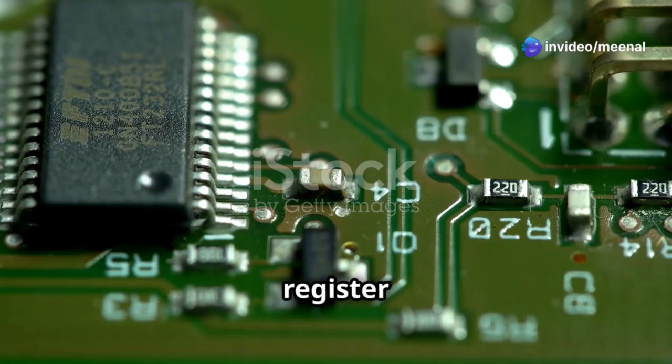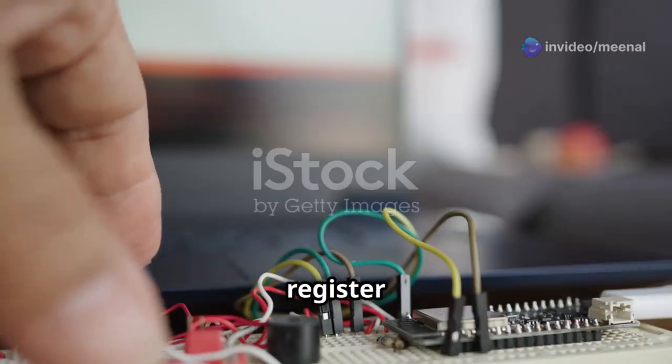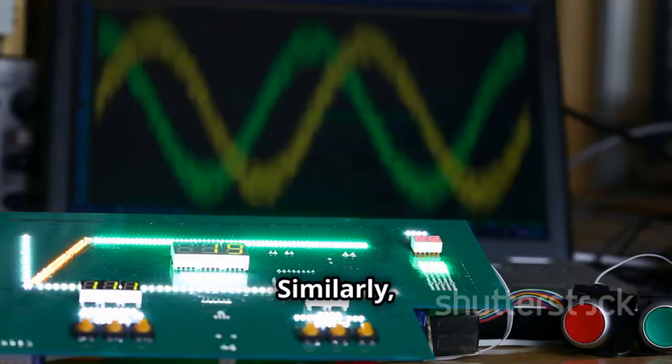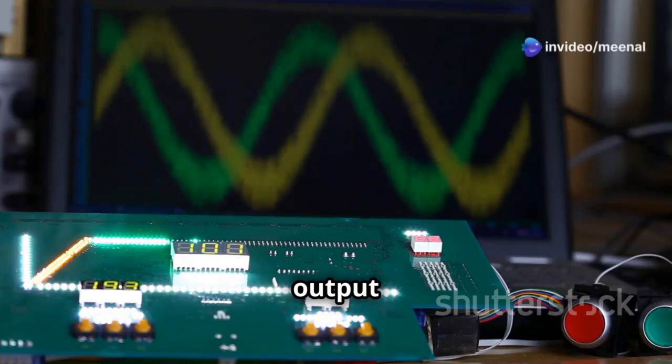The SISO shift register is the simplest form of a shift register. Data enters the register serially, one bit at a time, through a single input line. Similarly, data exits the register serially through a single output line.